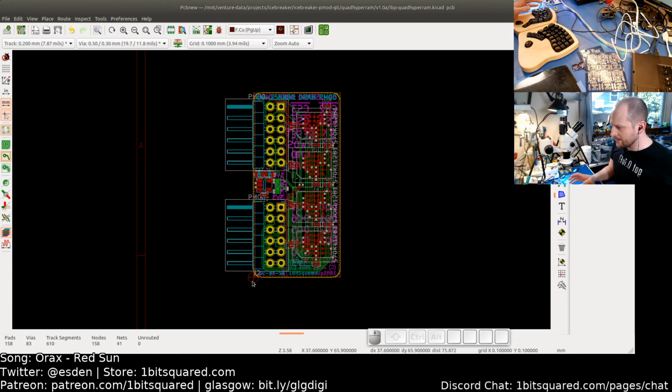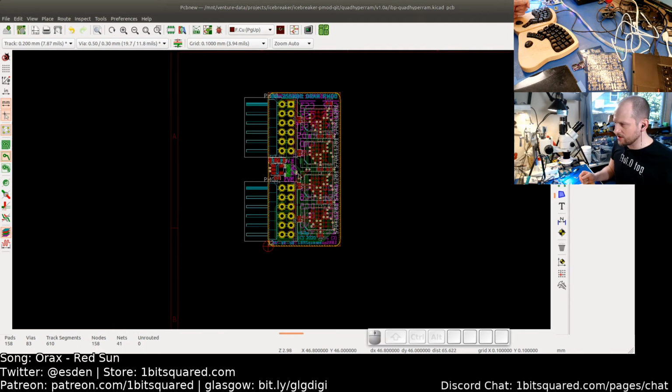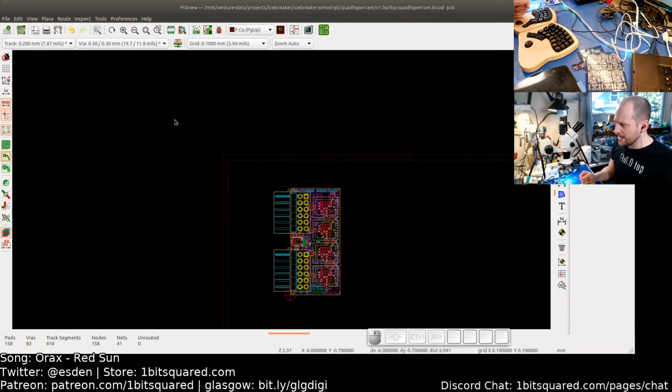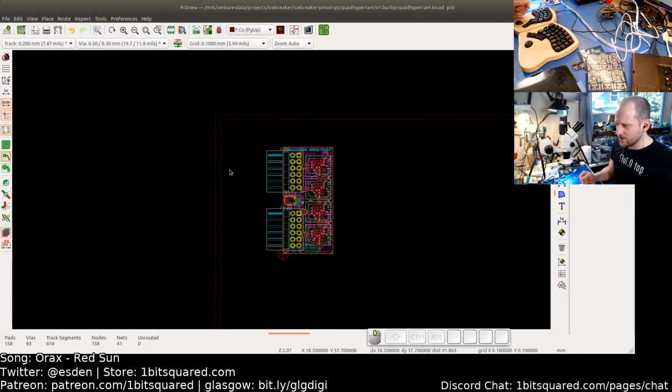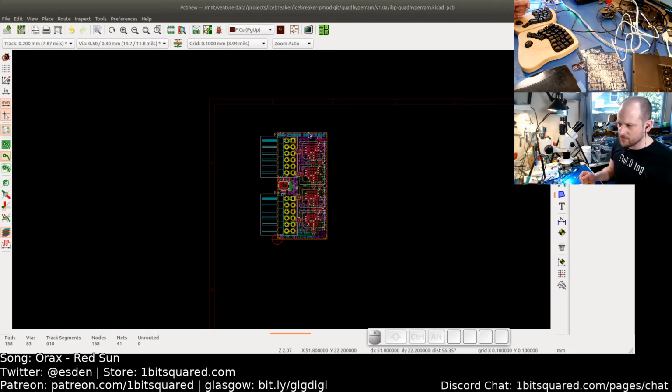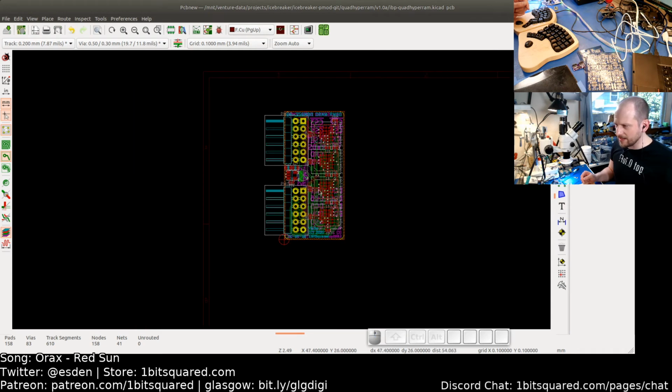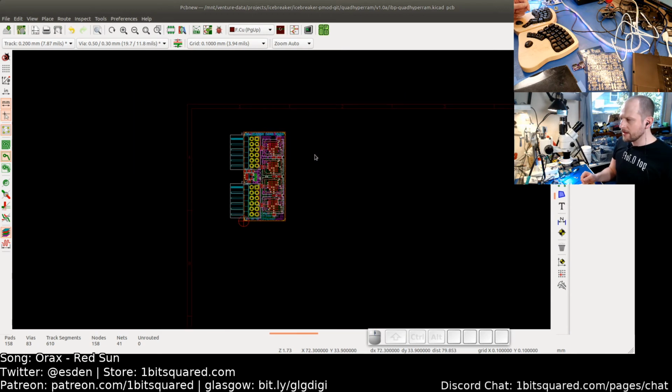But that's why, if I actually set up the pick and place machine, these crosses will end up in a corner of the board, because otherwise all the part positions are relative to a 0 that is located somewhere here, which is very arbitrary and really hard to read the coordinates if you want to debug something. So it is better to place it in some more PCB corner related spot. So yeah, that would be it.